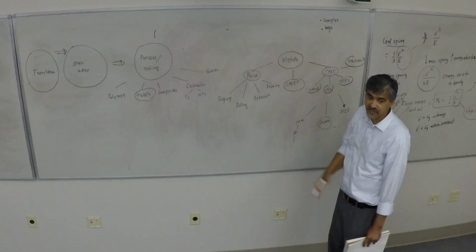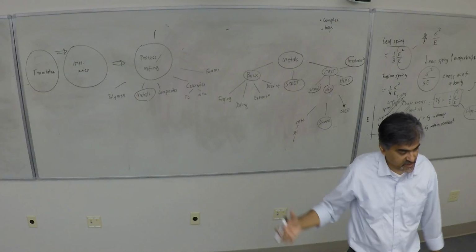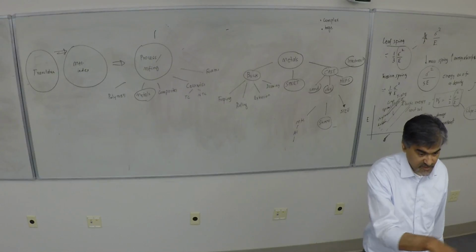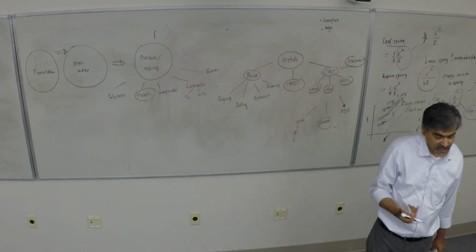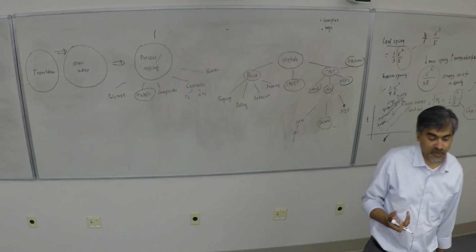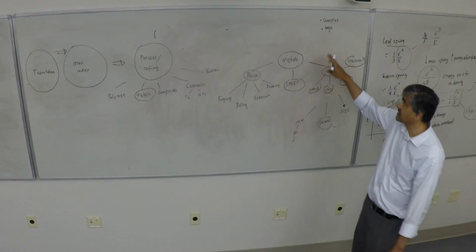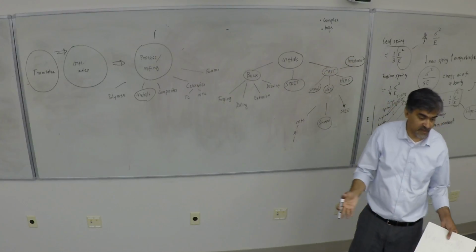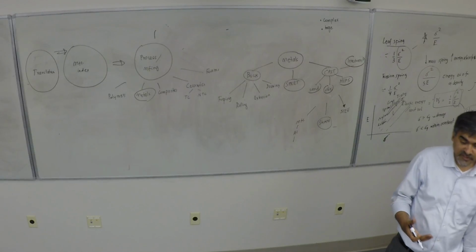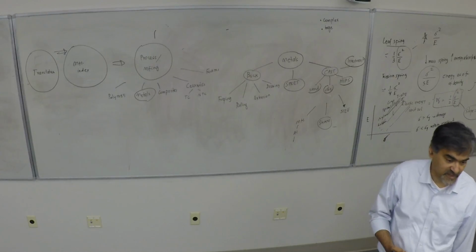So when the part is intricate in geometry, has a lot of ribs and a lot of steps and these trusses and intersections, then you want a metal which flows to those areas and fills the gap. But at the same time, you can't get the level of accuracy like making a wristwatch part, because the process just doesn't lend itself to that. You need to go for micro precision processing to do something like that. So large parts like machine foundations or boat propellers, or stakes that are buried in the ground. So components which do the function for that scale, but you're not too concerned about very high precision on those parts. In that case, it works.